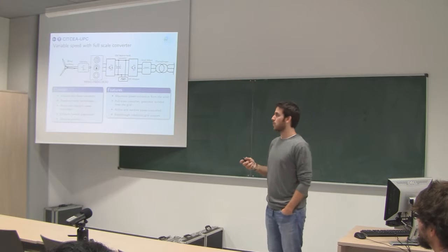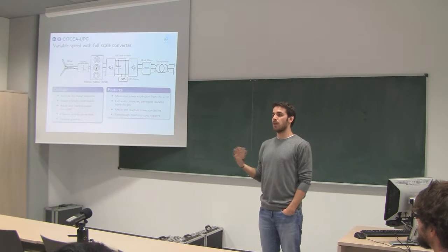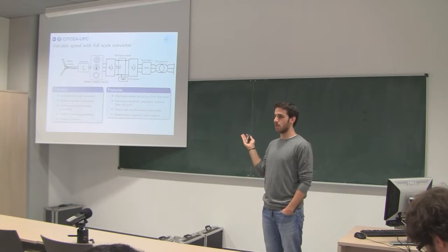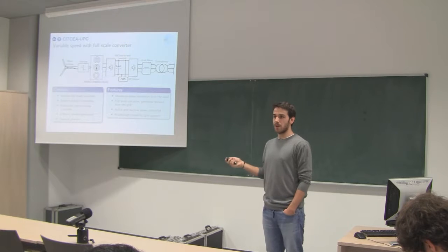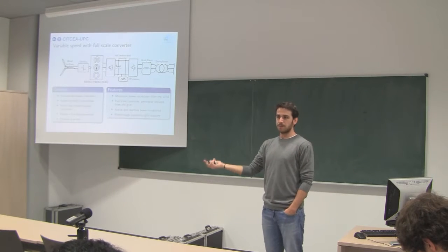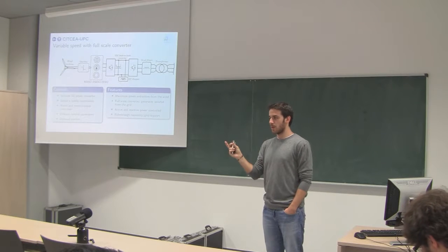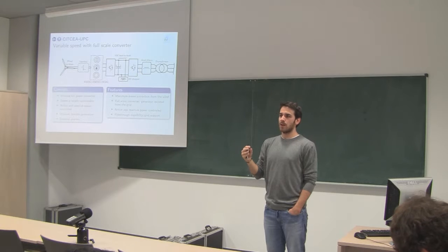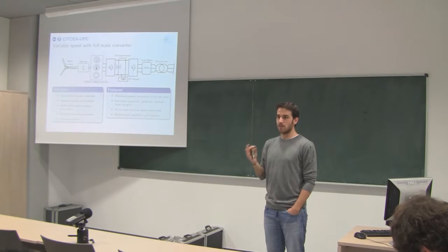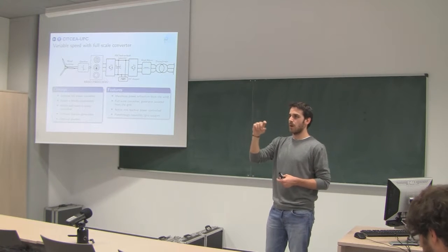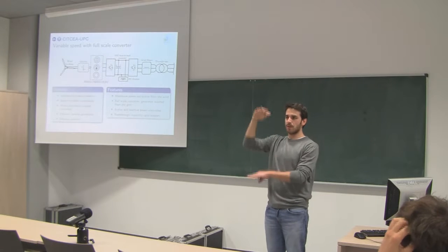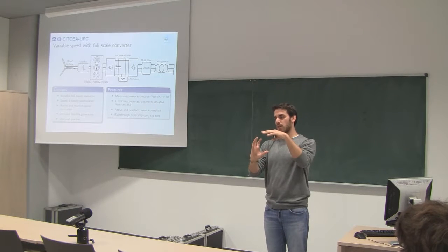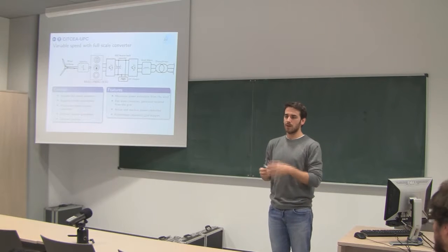I would say before that, first of all, there are not so many HVDC links. If you have an onshore system, you will definitely go for this topology: you invert again to AC, put a transformer there, and that's all. But if you have an HVDC link, as you say, everything is in the research stage, so nothing is installed like that, and there is not even a clear answer about which are the best DC-DC converters to be installed. There are proposals of connecting turbines in series to have a higher voltage, with a DC-DC converter to have isolation, then gathering several DC outputs of several wind turbines and elevating the power to a higher voltage.